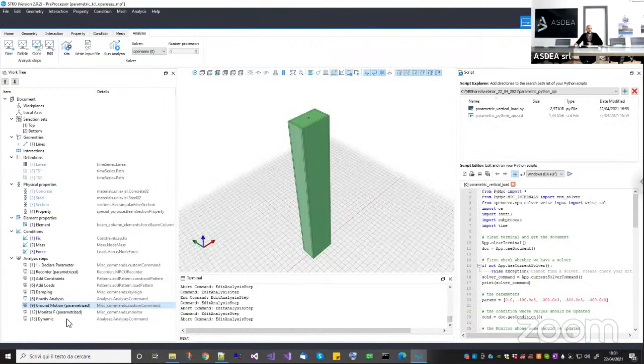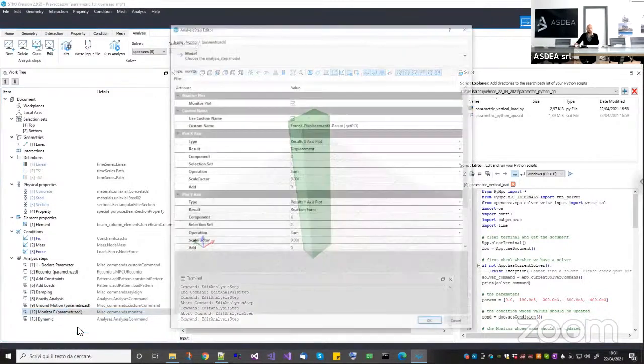The only last thing that we need to parameterize is the name of the monitor. As I said, because if you leave it with the same name on all the processors, it will monitor only one of them. Okay, so the first one that tries to open that file. Instead, we want to monitor all of them so that we can see all the monitor graphs in the same monitor widget.